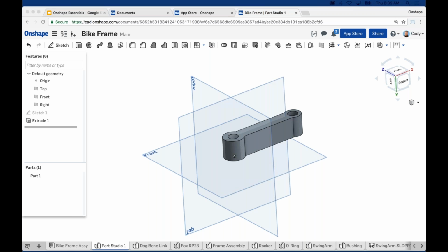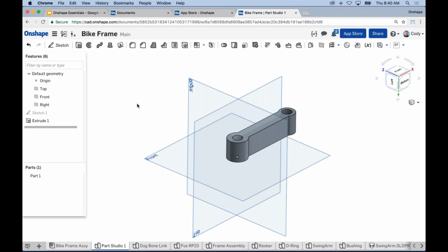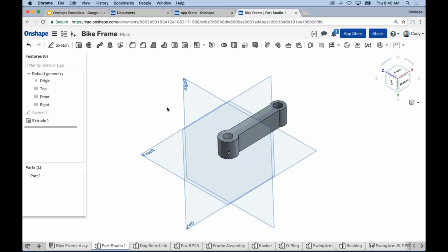Can we come back in the timeline and disassociate, delete the symmetry between the circles, and then continue to work on the actual design with the extrude? Yes, you can always go back into a feature, or a sketch.